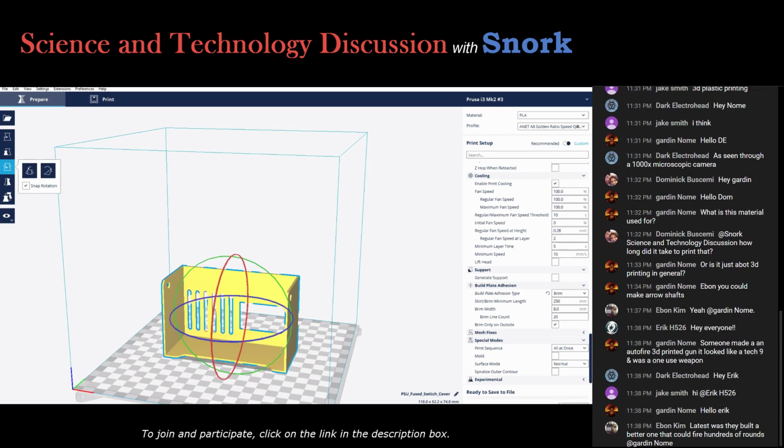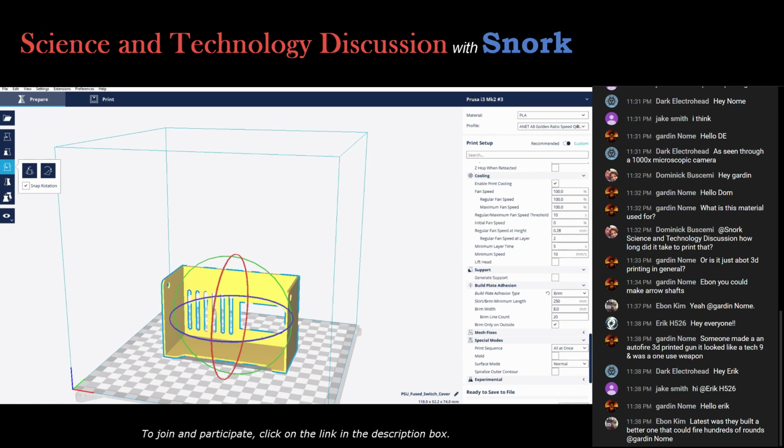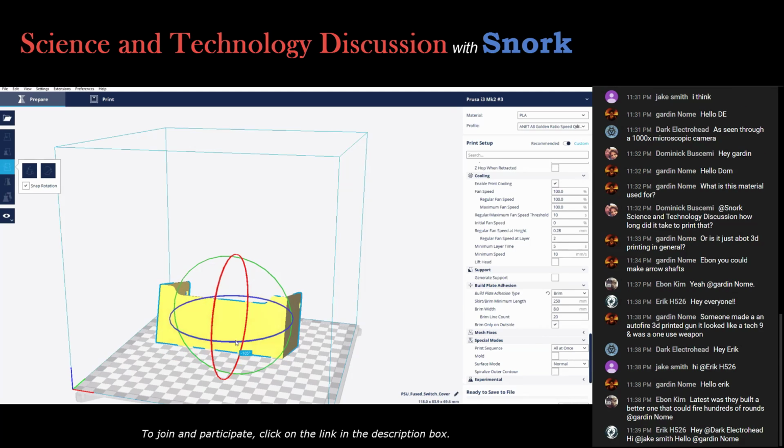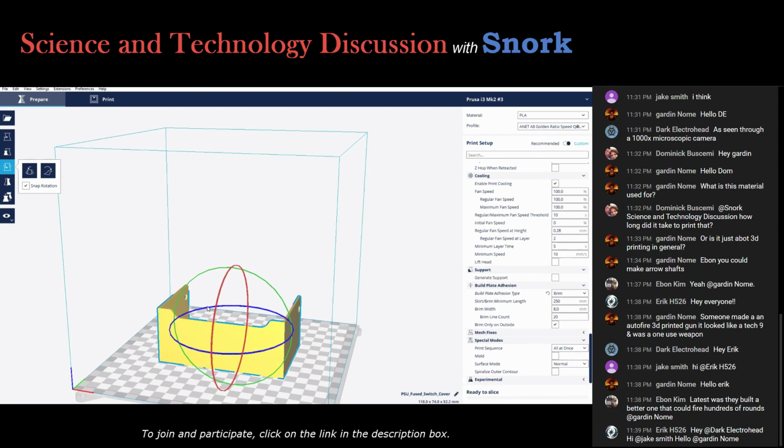Not only that, but areas that are exactly flat and are unsupported tend to not print well, tend to sag and whatever like that. So I try to avoid unsupported objects with more than a 45-degree angle. Now, a light circle can do, because it starts off real thick. But as you can see, I set this back down there. It's going to take almost an hour shorter. I could even make it worse.